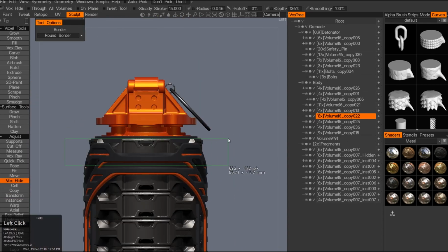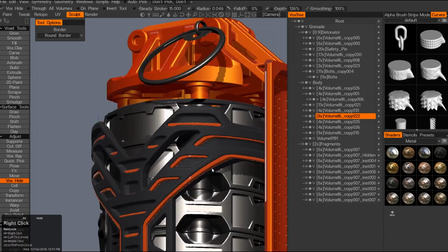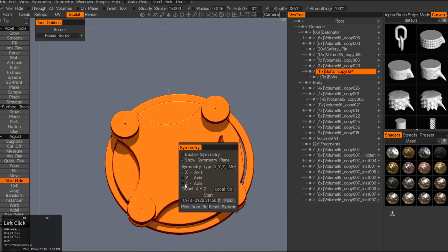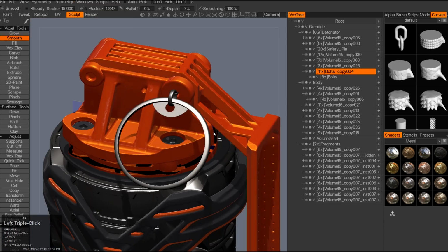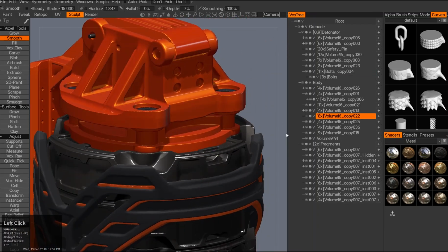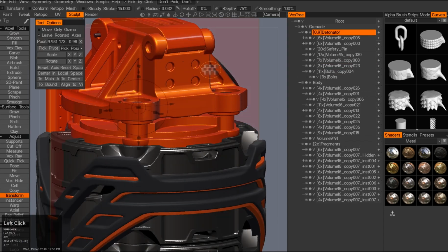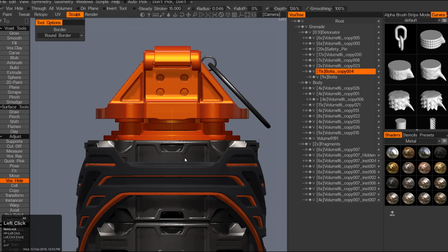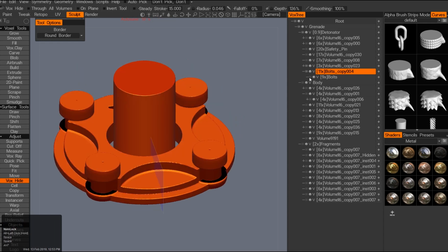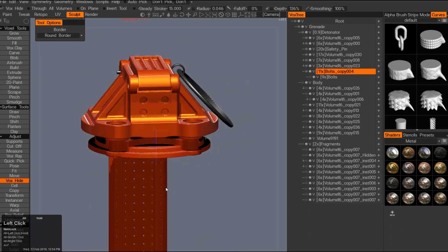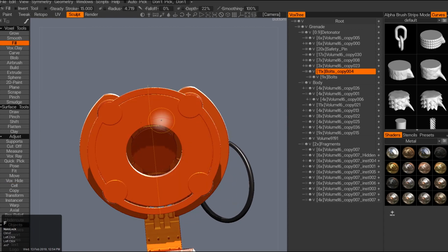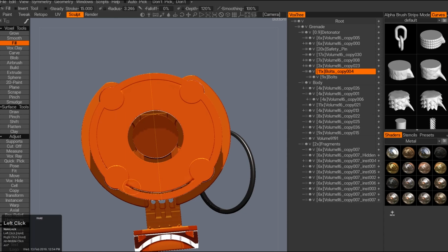So this particular piece is just like a rubber ring to hold everything together. And you can see there is a hole. I had a hole right there on one of those columns. What I had to do, I either did a voxel to surface and then back, or I did a symmetrical copy. If I have those bugs where some polygons start to disappear, you either have to transform them from voxels to surface and back, or just essentially do a symmetrical copy. I don't know why they appear, or how to deal with them, other than carefully doing a symmetric copy from another side, or turning them into surface and back into normal polygons. So yeah, it's a bit tricky.